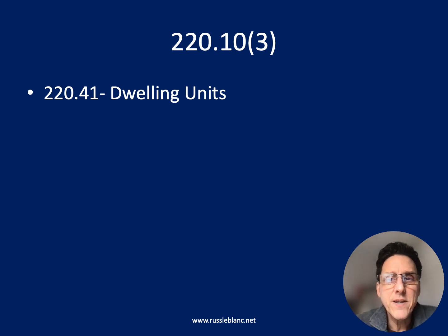220.10 number 3 says for dwelling units, you have to look at 220.41, which is actually part 3, feeders. So we are going to use the feeder calculation method for calculating branch circuit loads in dwellings. All right? That's what we're going to do.